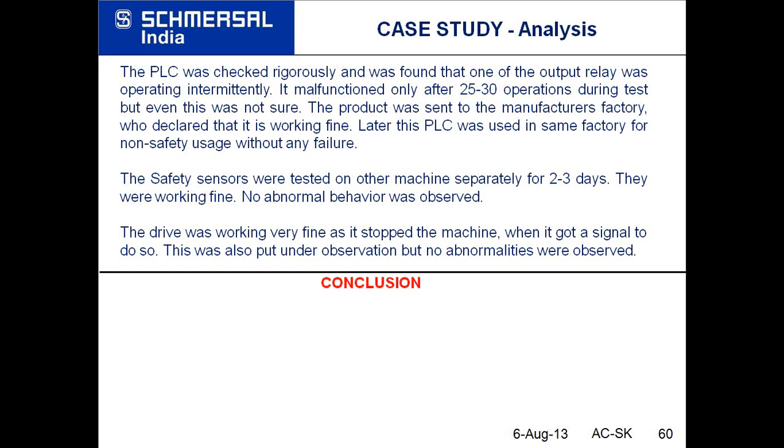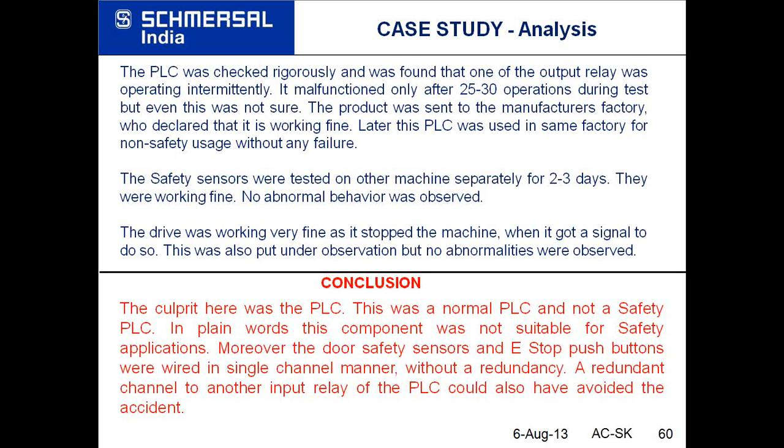So the conclusion is the culprit here was the PLC. This was a normal PLC and not a safety PLC. In plain words, this component was not suitable for safety applications. It was not a proven component as per control category 1.